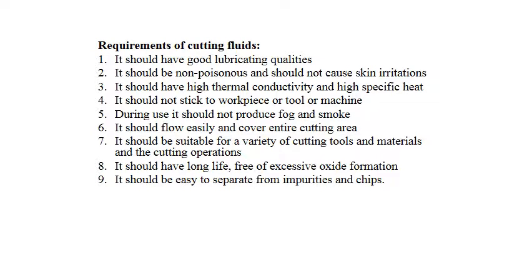Requirement of the cutting fluids. It should have good lubricant qualities. It should be non-poisonous and should not cause skin irritation. It should have high thermal conductivity and high specific heat. It should not stick the workpiece to the tool or machine. During use, it should not produce fog and smoke. It should flow easily over the entire cutting area.